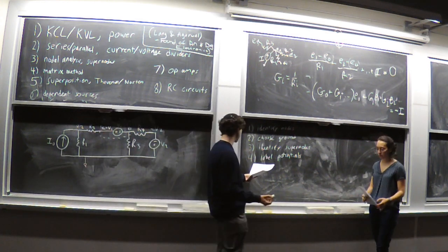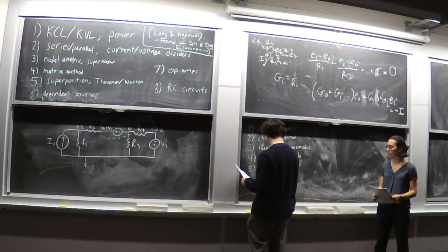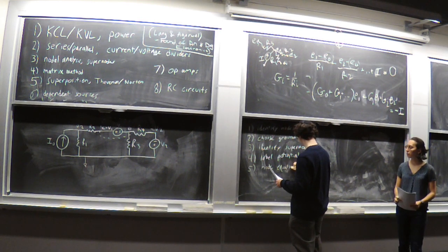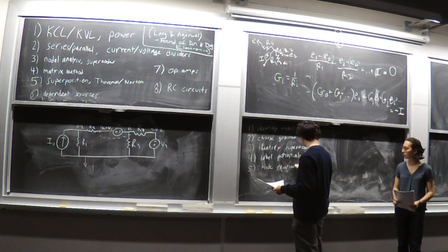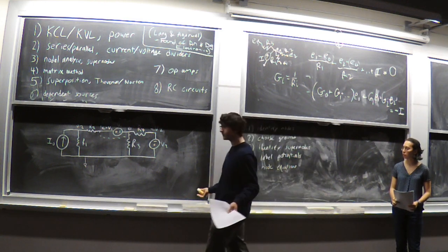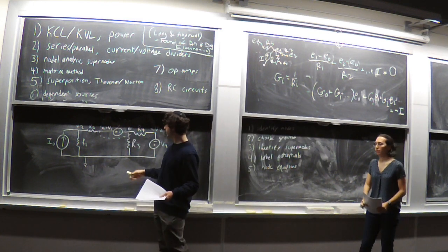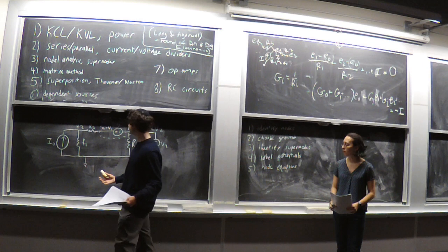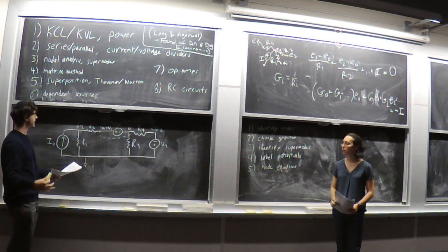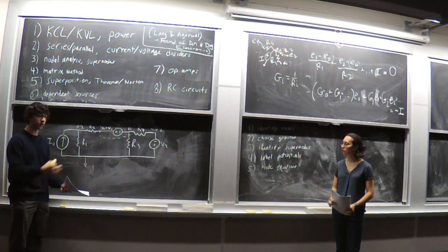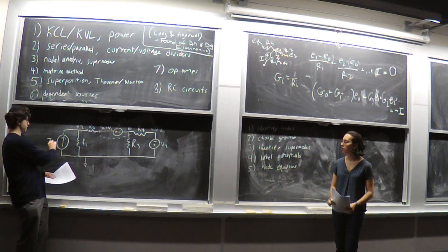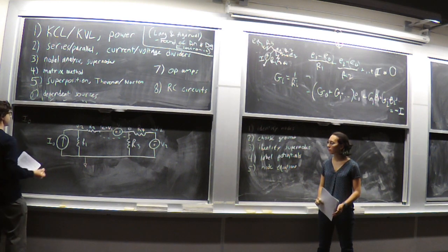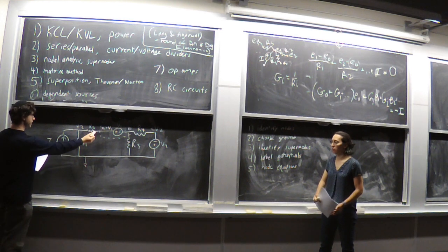So once we've done all of that, the next step is to write out the node equations. Hannah was explaining this before. For this circuit in particular, we just have these two nodes that we have to worry about. We have our giant supernode, and then we have E2. Let's start with E2, just because it's a standard node. So at E2, the first thing is how many different sources of current do we have going into this node? We have this independent current source. So that's going to be I0. We have this resistor, and we have this resistor.